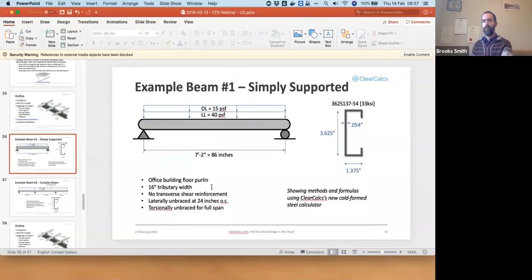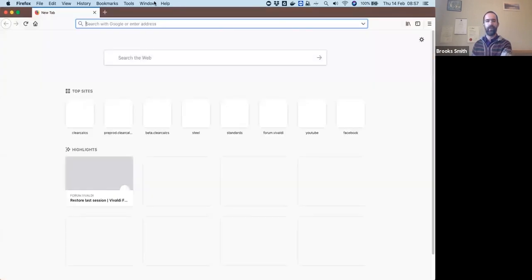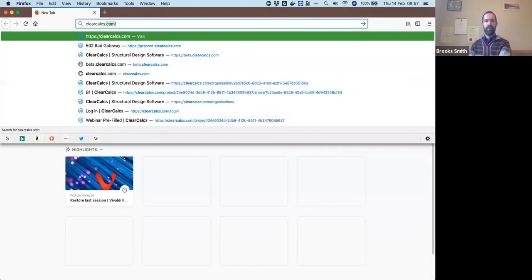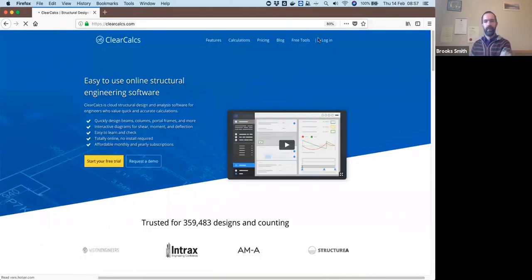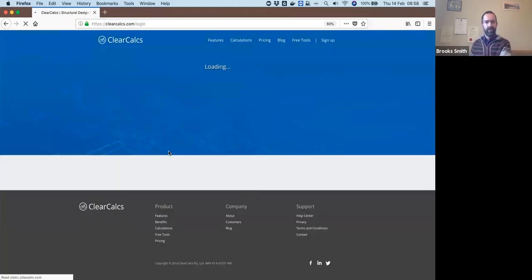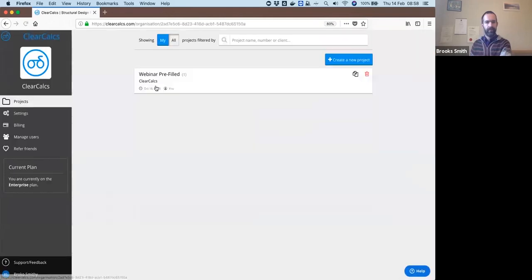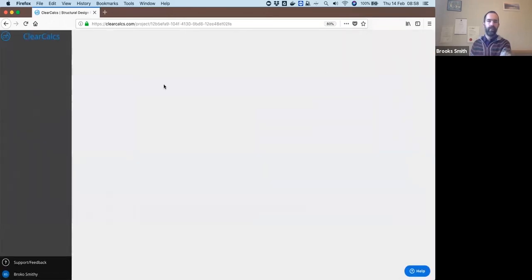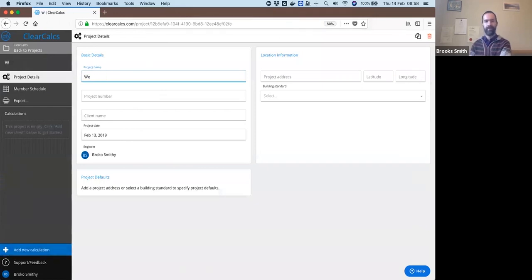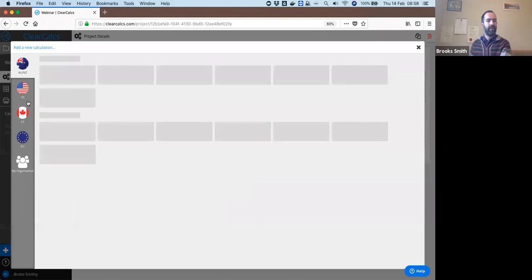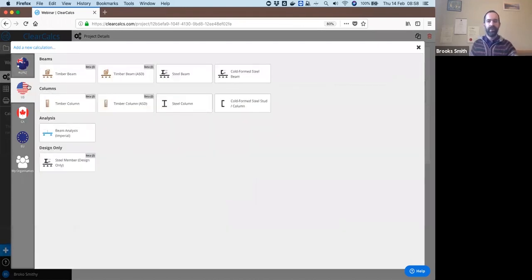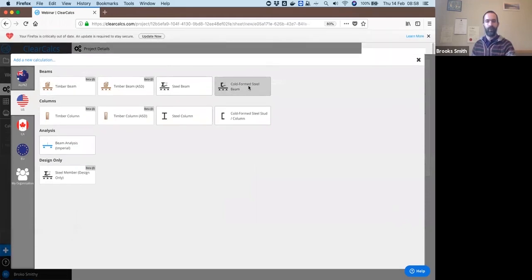So I'm going to go into ClearCalcs to show the example as to how this works here. Show how you go through these equations. So logging into ClearCalcs at clearcalcs.com. I'll create a new project. Just call it webinar for now. Project number, client name, and whatnot are optional. And then I'll add a new calculation. We offer a number of different types of calculations, timber, steel, cold form. I'll select cold form steel beam.